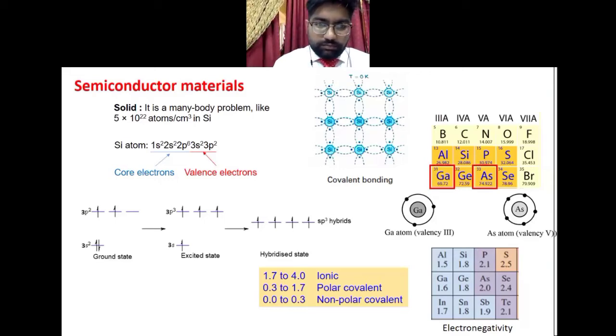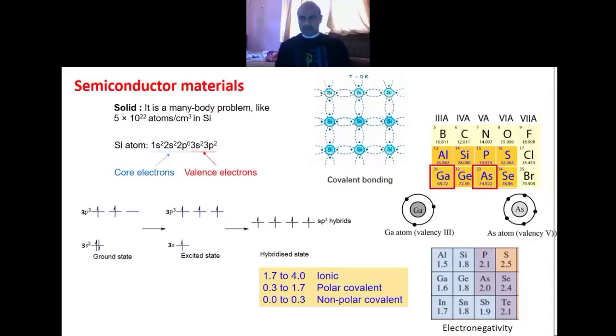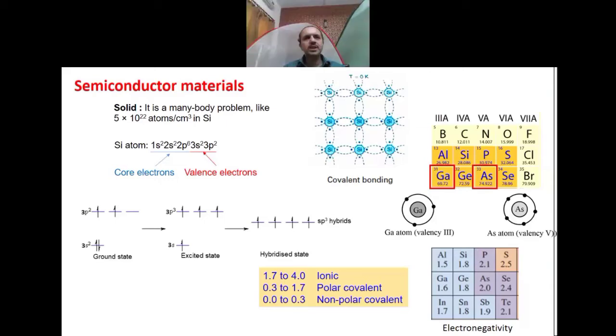When I'm talking about silicon or gallium nitride, this is at the surface where we are making the contacts, so it usually doesn't matter in which direction. But if they are anisotropic materials, many of these ferroelectric materials or piezoelectric materials are anisotropic, then you have to keep in mind the direction.